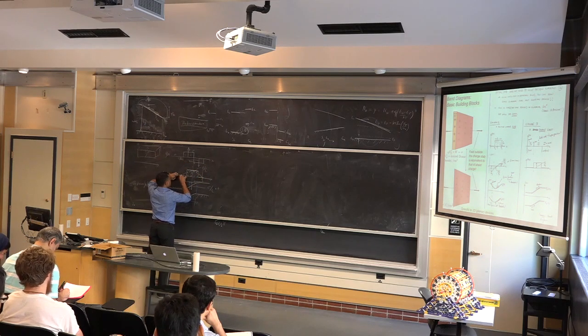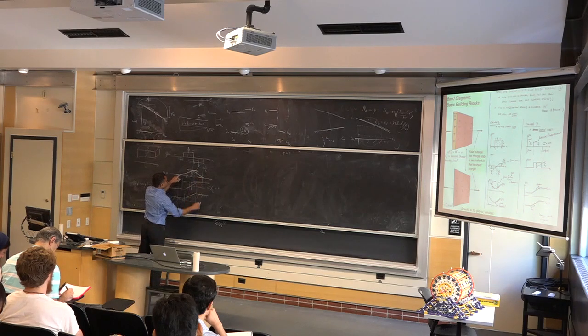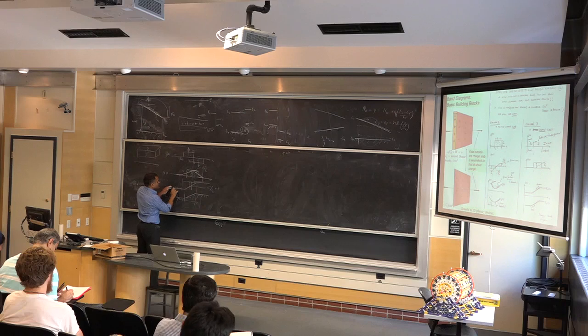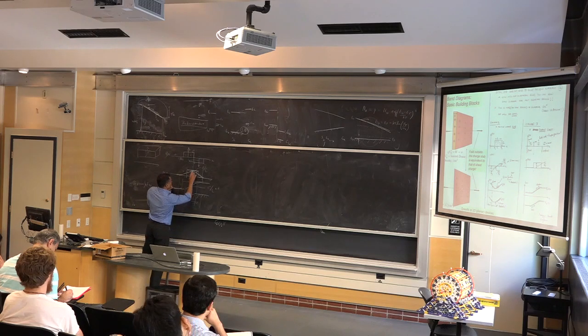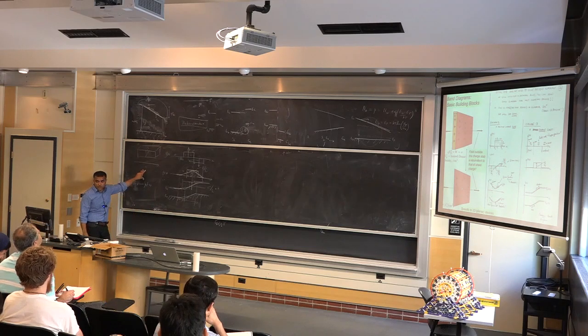Does that make sense? So instead of what we had before, the field will not be constant, it will be a triangle like that now. And what will happen to the potential is you have a linear function, so the potential will change parabolically. If this is a function of x, you integrate it, you get x squared and some linear term as well. So it will change parabolically, and if I were to sketch it, it's going to look something like that. And I think you will make the connection that this is exactly the picture of a p-n junction.